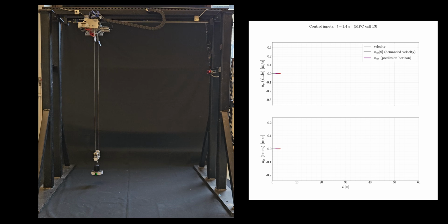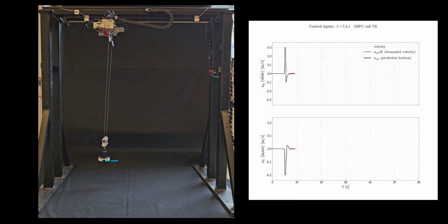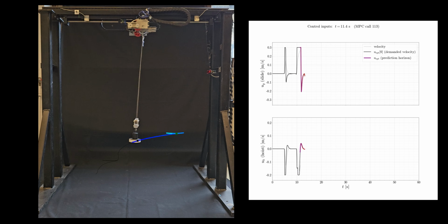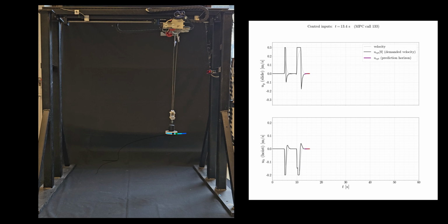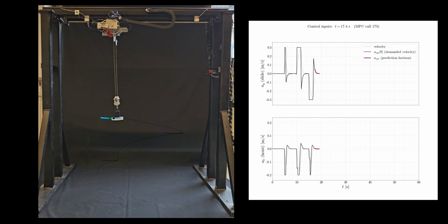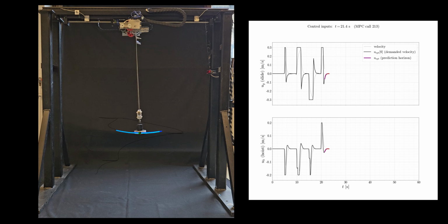The black dot shows the position of the load based on the measurements. The green star marks the target state for the load. In blue, you can see the trajectory predicted by the controller. On the right, the plots show the control inputs over the prediction horizon. As you can see, the cart and the hoist reach their targets, but the load keeps oscillating since the controller ignores it.